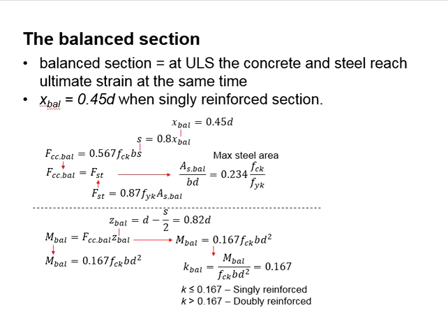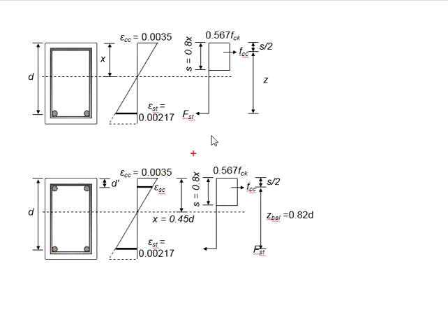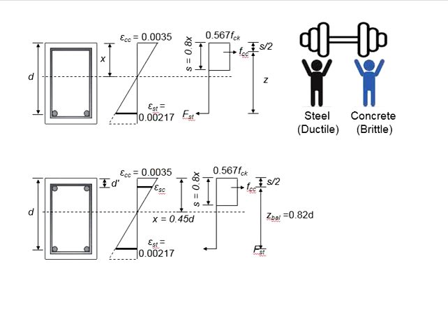Now, you might want to ask, what happens if you really need that amount of reinforcement in the member? When the maximum steel area has been reached, are any countermeasures needed? Yes, the section will transform from a singly reinforced section into a doubly reinforced section. To make it simple, you may also observe from this example.